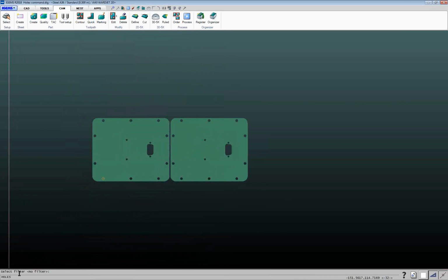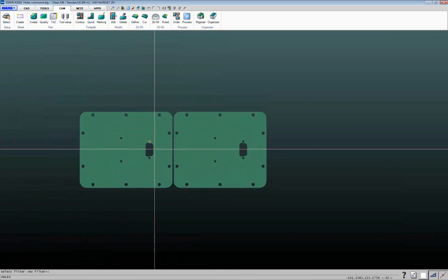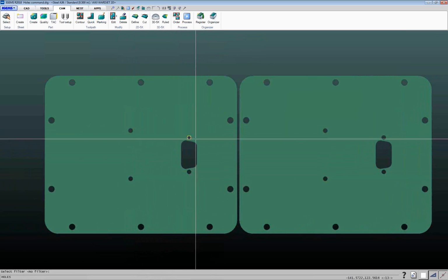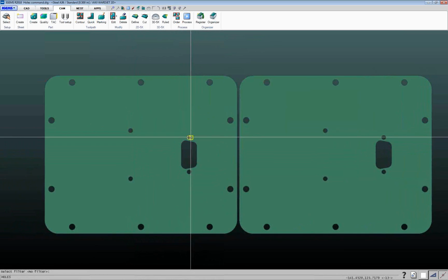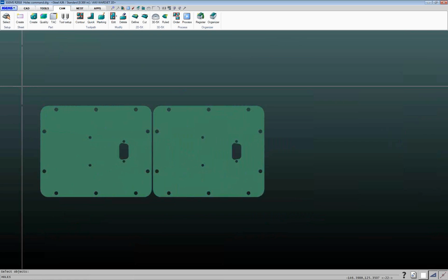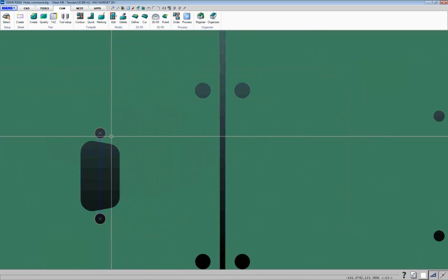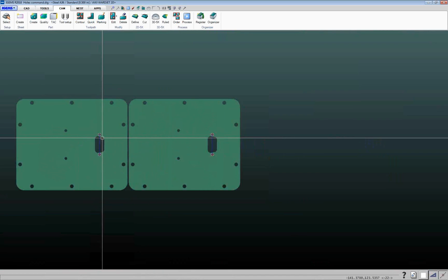After you start the command, down here at the bottom it says select filter. And so basically if there was just a certain size hole that you wanted to drill rather than drill and cut or cut, you can say, all right, I want to drill holes of that size. And now it's prompting me to select objects. So then if I go around and click both these parts, it's going to find holes of that same size, and then it's going to add the drilling command to those holes.